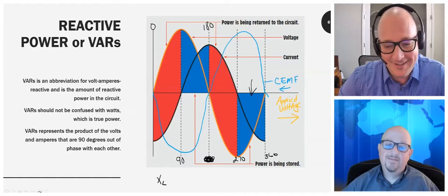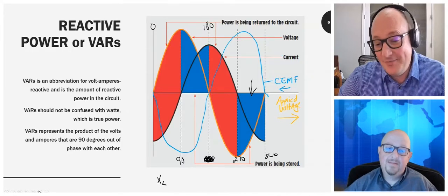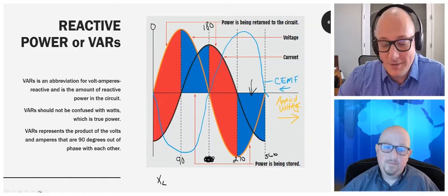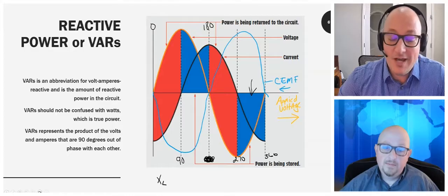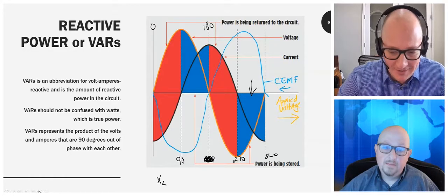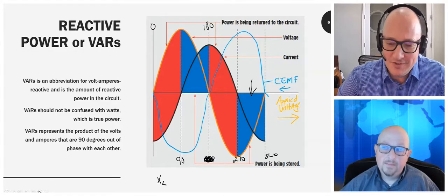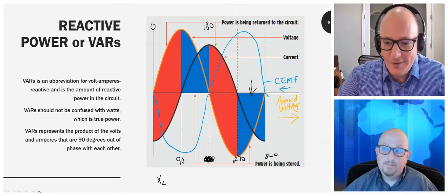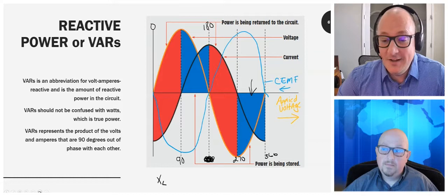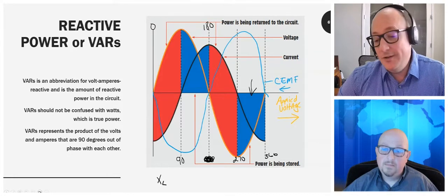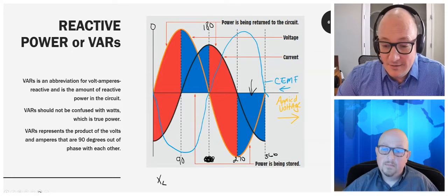You could have a lamp that's of low wattage, but it might have a really poor power factor. We all know the VA value really isn't all that good because the efficiency is really poor, and all you're worried about is the wattage. Well, the reality is how much current's being put on those transmission lines. That's VA. That's the apparent power.